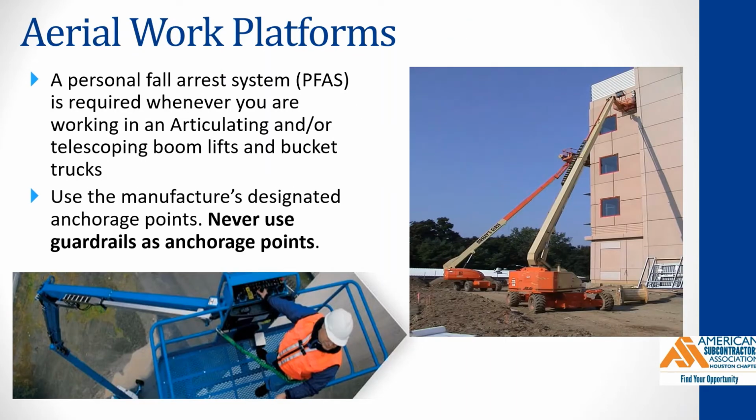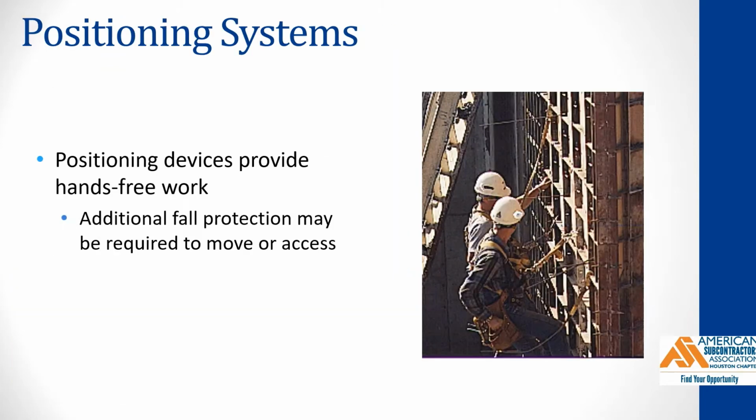Aerial work platforms have their own fall protection challenges. A personal fall arrest system, or PFAS, is required whenever you are working in an articulating or telescopic boom lift and bucket truck. Use the manufacturer's designated anchor points. Never use the guardrail as an anchor point. Consult the manufacturer's user manual as needed.